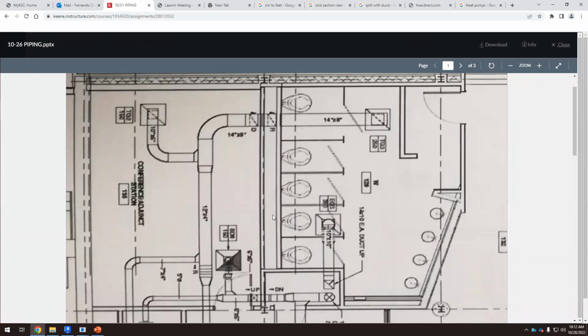We're going to deal today with the hot water supply. So we need this drainage pipe going down, but at the same time we need another pipe going up. They have to be connected because we have to introduce that air here so that we don't have jams in this pipe. So at the end we have something that will be like this.